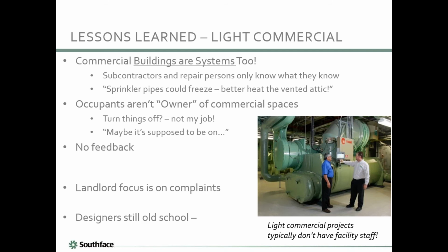Yep. And then perhaps often a trust in automation that may not be in your best interest from an energy use standpoint. That's a really good point. We've learned that lots of times, especially in commercial buildings, if you have automatic lighting controls, you may need to go around and make sure that your outside lights aren't on in the middle of the afternoon. If you've got programmable thermostats, someone actually needs to look at how they've been programmed, because the schedules may have changed from when they were programmed 3 years ago. But they may say HOLD, hold the temperature all the time.